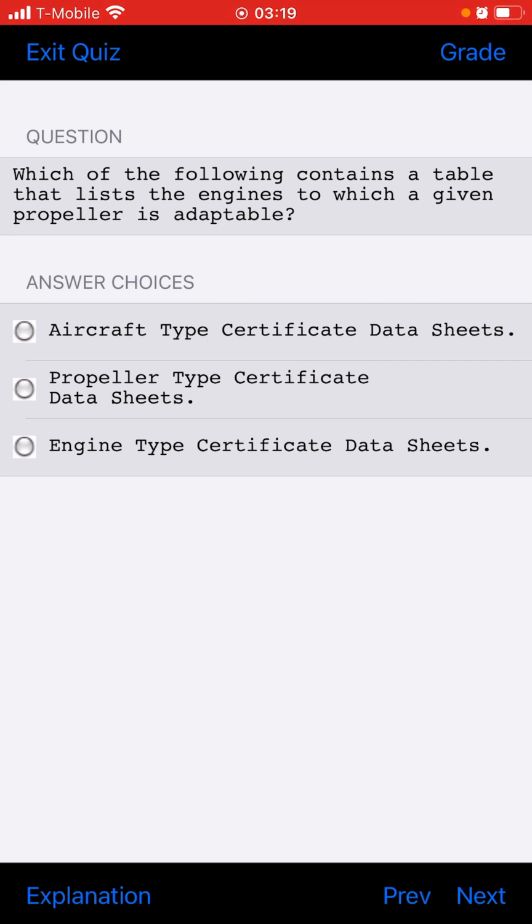14 CFR Part 23. Which federal aviation regulation specifies that each resettable circuit protective device requires a manual operation to restore service after the device has interrupted the circuit? A manual operation is required to restore service after tripping.